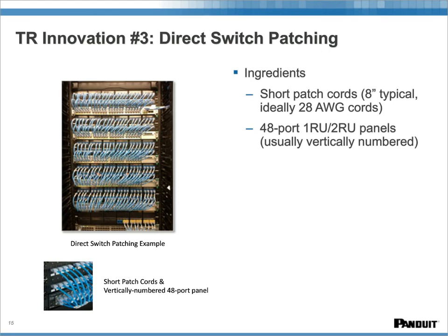The one consideration that I'll just make you aware of, and we covered this quite a bit in our presentation about 6 months ago on the 28 gauge patch cords, is that the bundle sizes, when a number of cords or horizontal cable are bundled together for any distance, might have to go down.